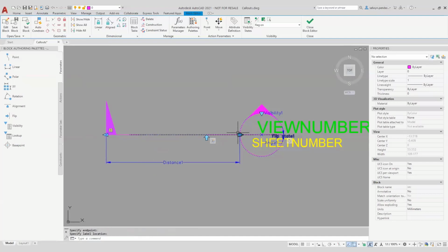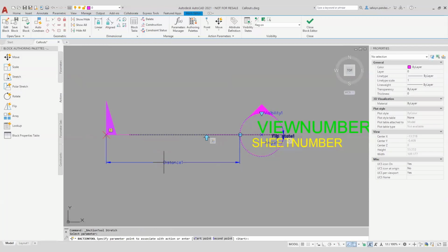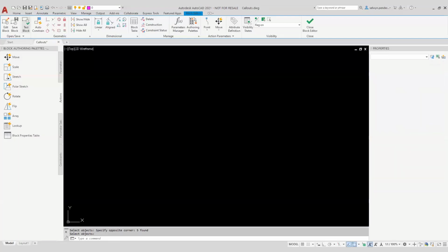very basic level, which, I've seen webcast videos, training, etc., where people just tend to jump in and they're showing you an extremely complicated drawing, and we're just trying to show you the simplicity of these things in a very simple fashion, so that you guys can go away and start to think, oh, actually, where can I apply these? Title sheets is a good one. So if you have title sheets that have different frames or different setups for the content that goes into the title sheet, you can use dynamic blocks there.